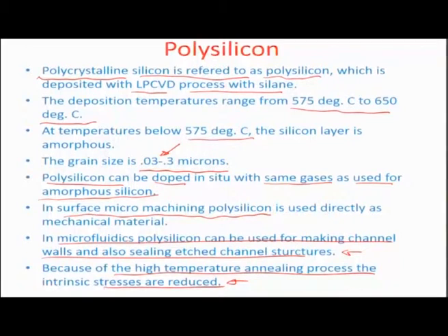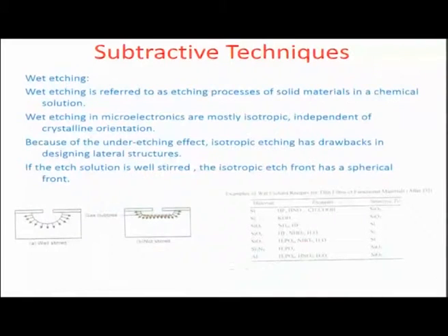So, silicon now can be obtained in single crystalline form directly from the growth process, or it can be grown using epitaxial methods, where you have deposition of silicon atom by atom, layer by layer, and then you have the third form, polysilicon, which is actually polycrystalline growth in multiple nucleating centers with grain boundaries, which is mechanically the most robust system of crystalline silicon that can exist. So, that is how silicon can coexist in its different forms.